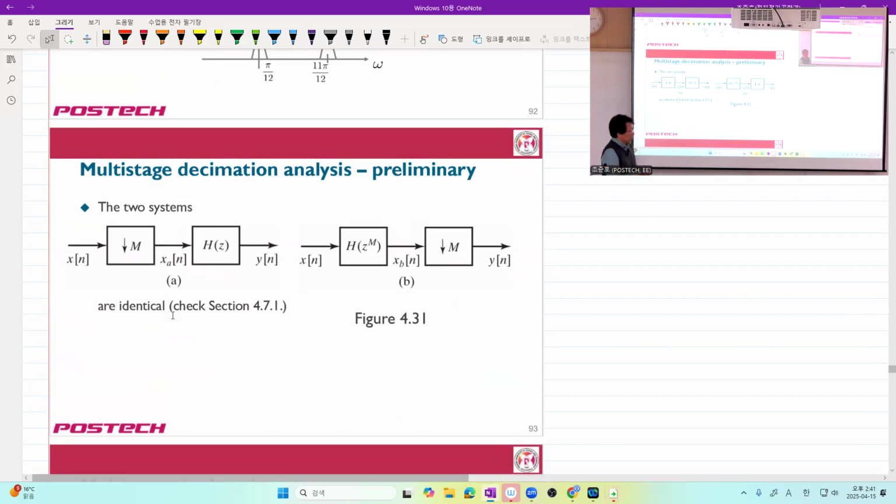By the way, even though these low pass filters, high pass filters, or band pass filters are in terms of the frequency, which means that we'd better focus on their DTFT. But the problem of DTFT is that it's kind of low dimensionality. We want to think in a higher dimension. So a simple way is to just replace DTFT with its Z transform.